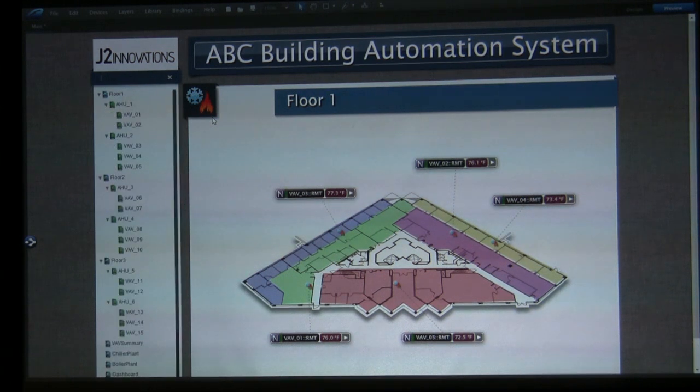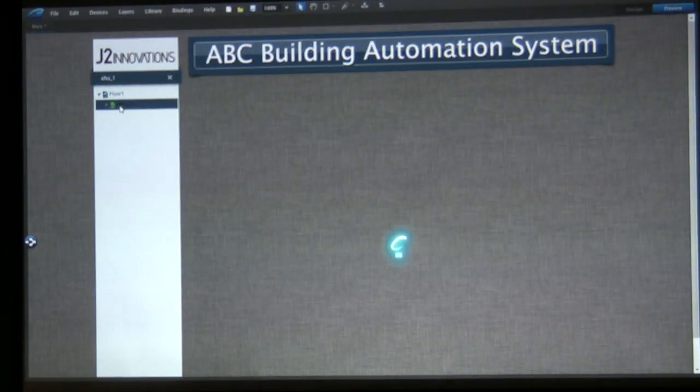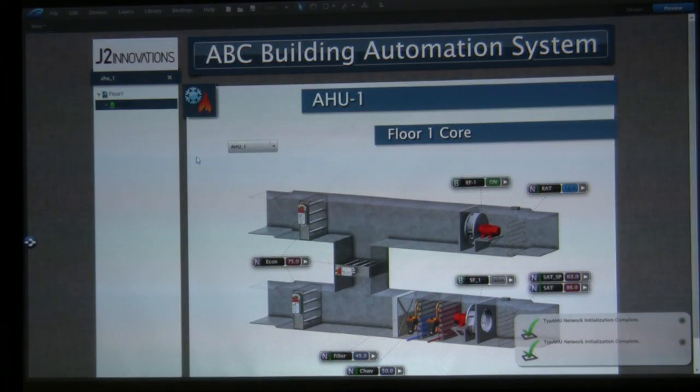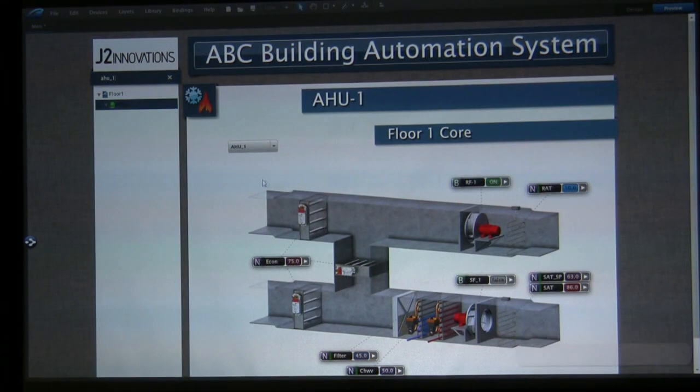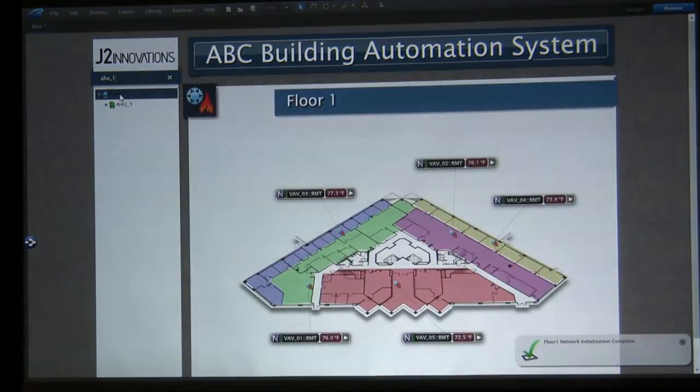It's underscore, not hyphen. Thank you. My demo has changed since last time. And that will then resolve not only that fin file or PX page, but it will then show the parent relationship. So in this case, air handler 1 is underneath floor 1. And so they can work their way down to air handler 1 and literally with one mouse click get there. And if they wanted to see correspondingly what's going on, because of the beauty of that parent-child relationship in nav files, they can go up to floor 1 and see what's going on at the floor level.